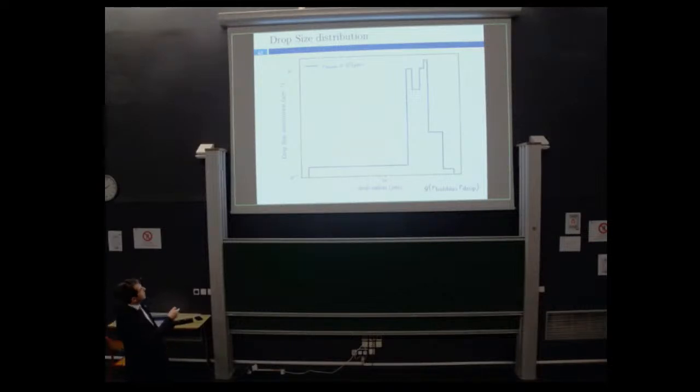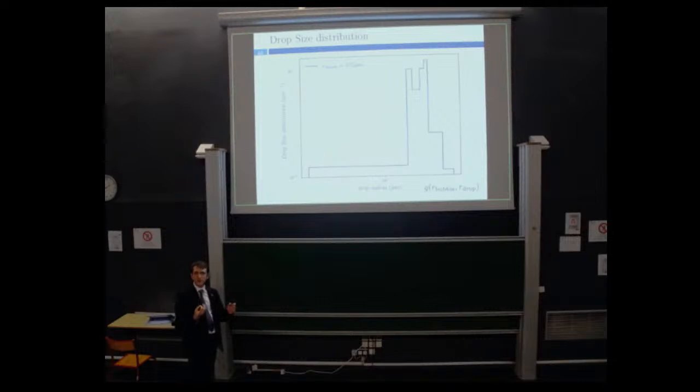And this is what I'm putting here, distribution of the droplet size as a function of the radius of the droplet. So here we've got our entire distribution for a bubble of approximately 0.2 millimeter of radius, with a peak here for a droplet of approximately 20 micrometers. So the distribution has a peak here, and then we spread around this peak. What is important to say is that we've done that for several bubble size. This gives us the distribution function, or if you take a slice of this distribution, the probability to get a droplet in this range.